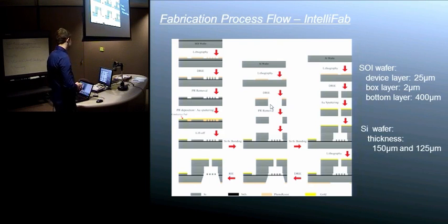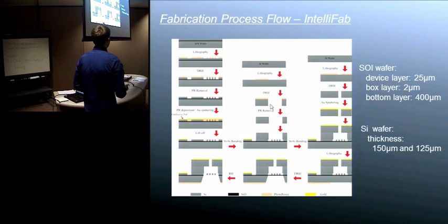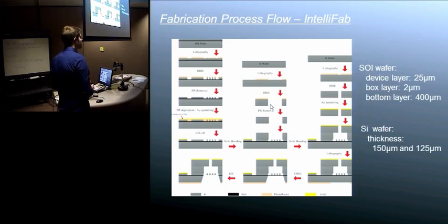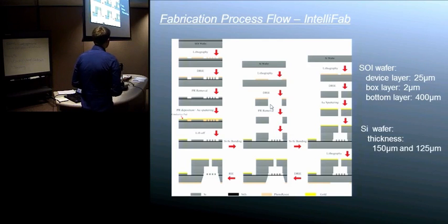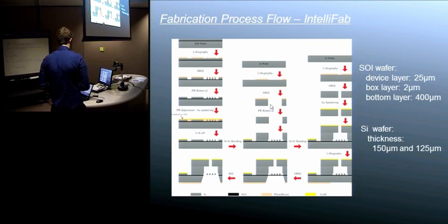With that tool, we focused more on dimensional differences, so for a comb drive, the width of the fingers and how that affects certain things in it. But if you wanted to change an angle, it would just involve more scripting with the VB scripts. But chances are we have several templates. One of the live demos will be using one of them, and just from looking at them, you can kind of infer how it works. And if you need any additional assistance, we have a VB scripting guide that we wrote specifically for Blueprint.